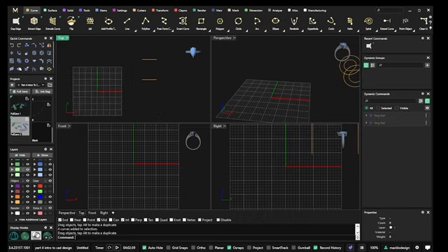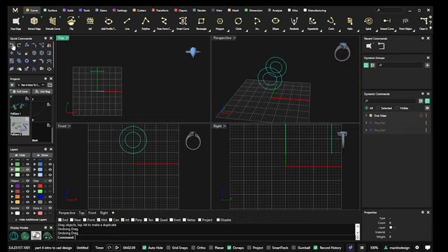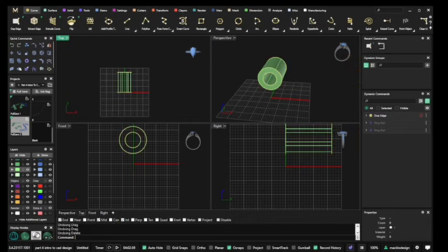Extract edge. All right, let's bring that solid back in, and I'm going to take my curves. I just surround them from the left side, and that way my extrusion does not come. And let me get a gumball on that. Gumball is on.